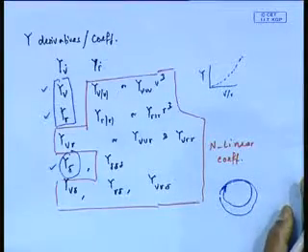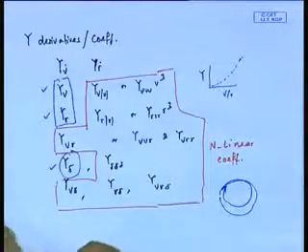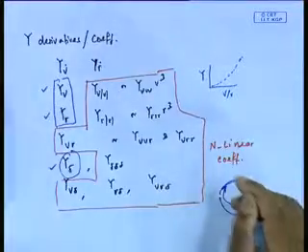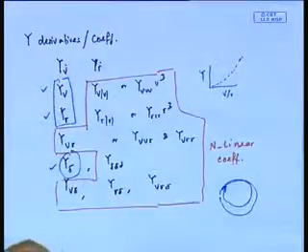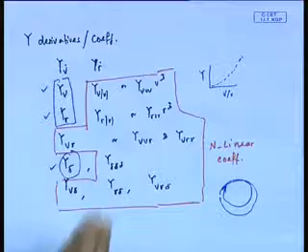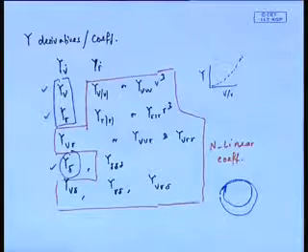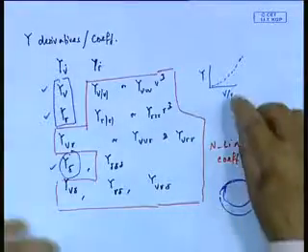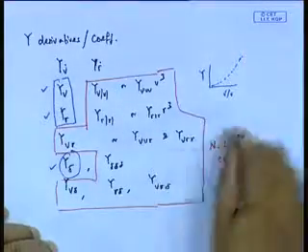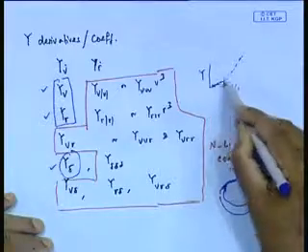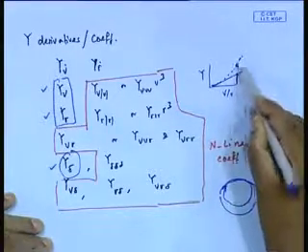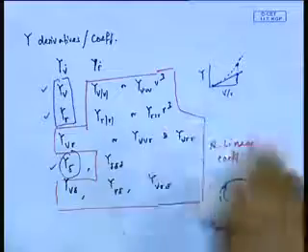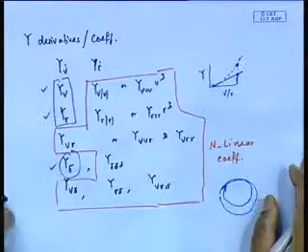So, I had an IMO requirement that my ship must turn within 5 ship lengths and all that stuff. If I could estimate them based on the linear derivatives, I will be more or less sure that the ship would meet the requirement, because nonlinear derivatives always tend to make it a smaller, tighter, faster turn. That also makes sense, because nonlinear forces go like that. In a linear model you are predicting my y force was this much, but actually the force is much larger. So, naturally that is normally so.